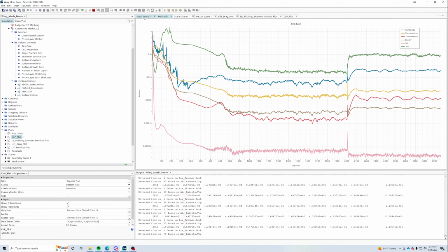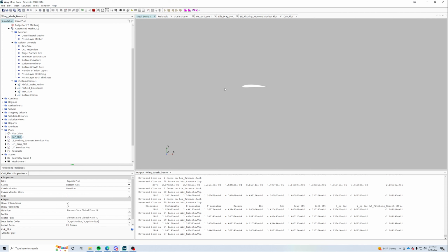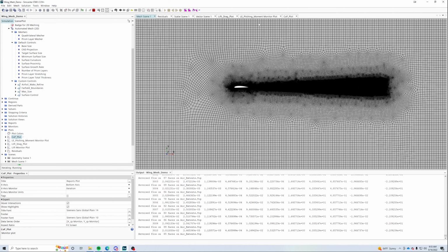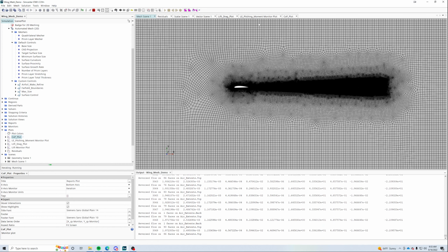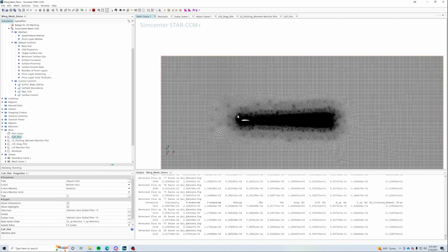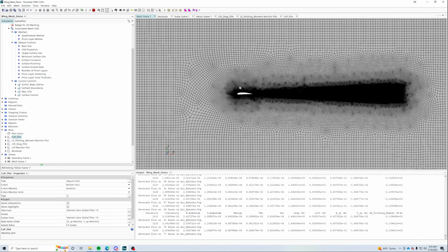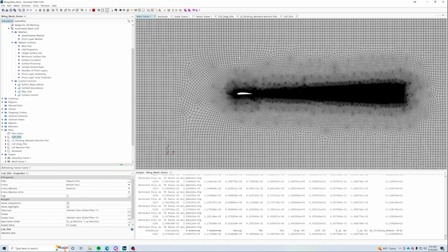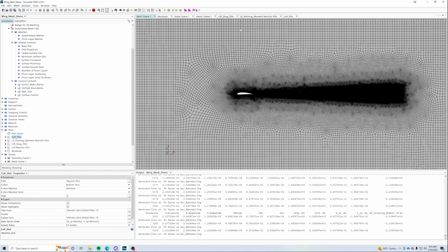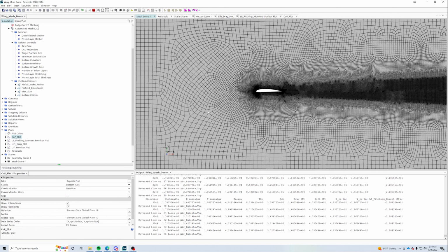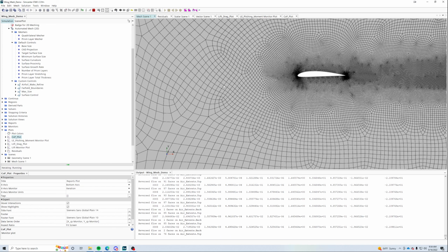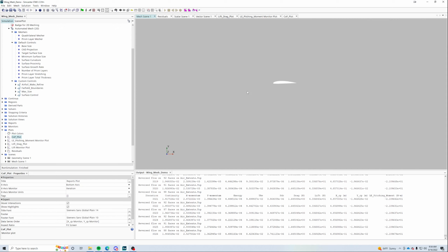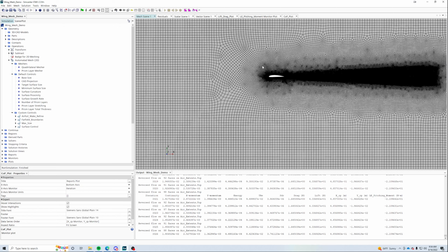And if you're dealing with something that's not very well defined, like an airfoil at low angles of attack, in two dimensions, quads can potentially get you in trouble. It's not the worst thing in the world, but I prefer in 2D polygons to quadrilaterals. Or, yeah, quadrilateral cells, so rectangles, essentially. Mostly rectangles with some deformed rectangles to make curvatures work. So this is a quadrilateral 2D mesh.